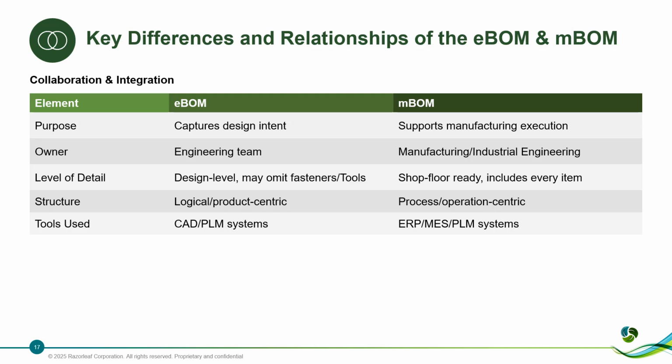The structure for the eBOM is logical and product centric. The mBOM is process and operations centric. For the tools used, the eBOM uses CAD and PLM systems. The mBOM typically uses ERP, MES, and PLM systems.